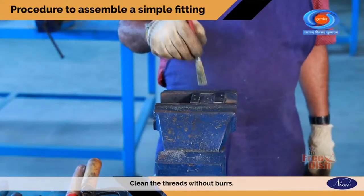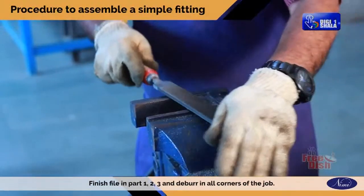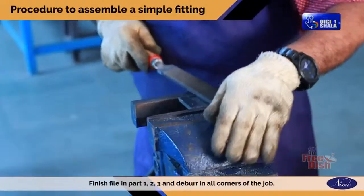Clean the threads without burrs. Finish file parts 1, 2, 3 and deburr all corners of the job.